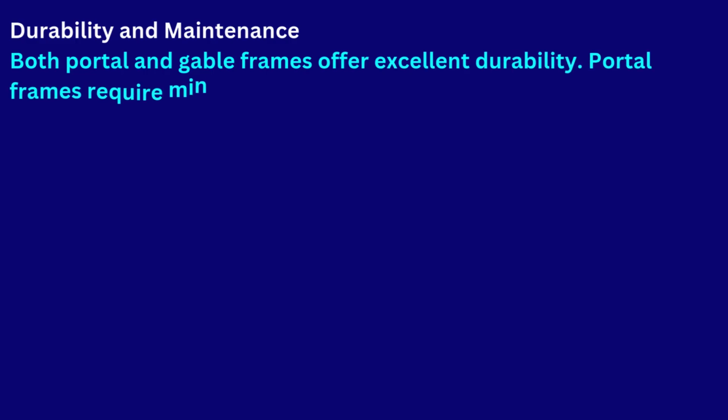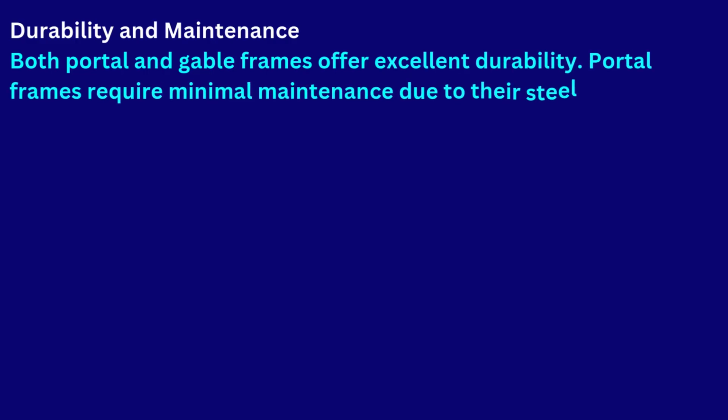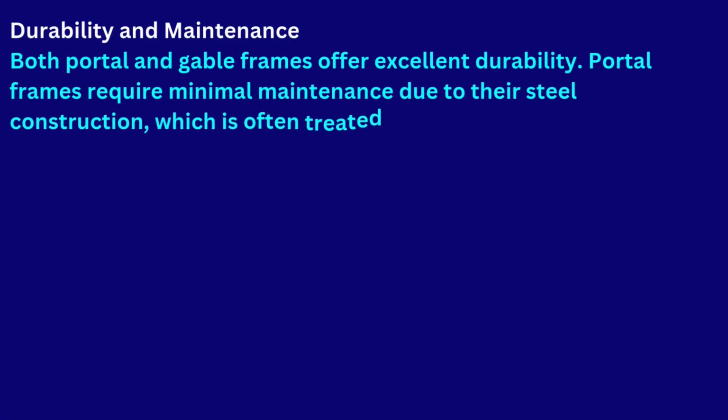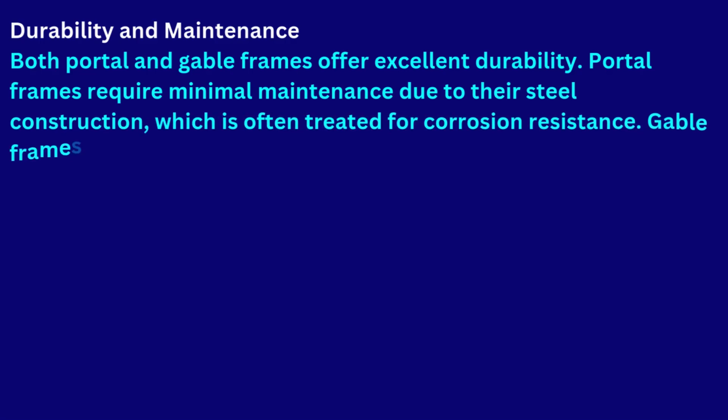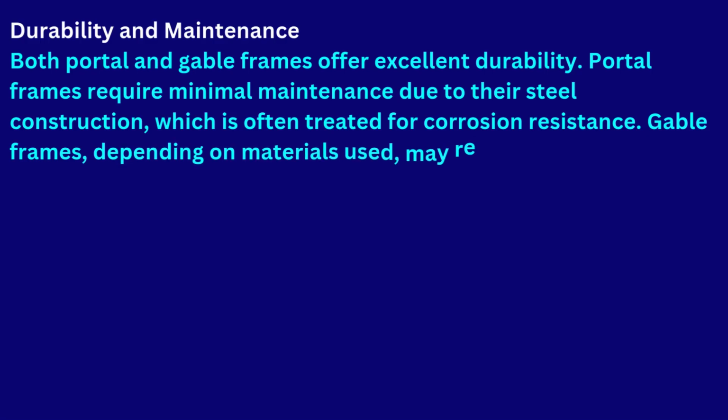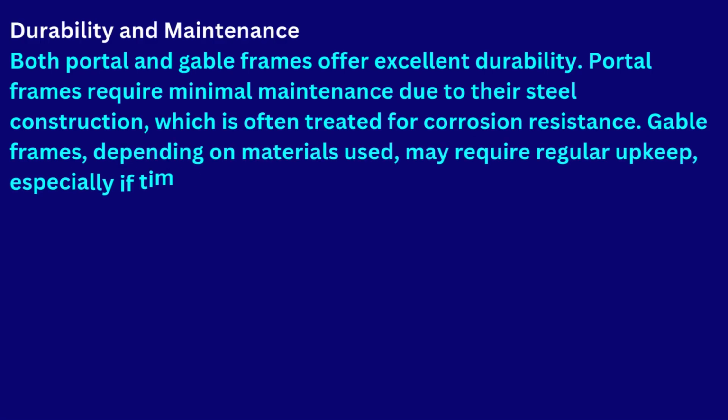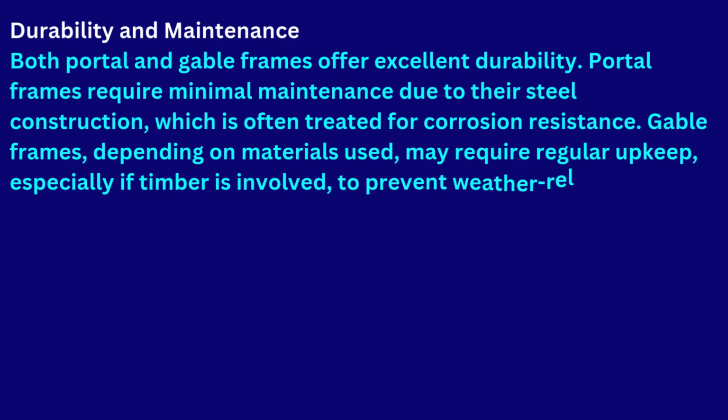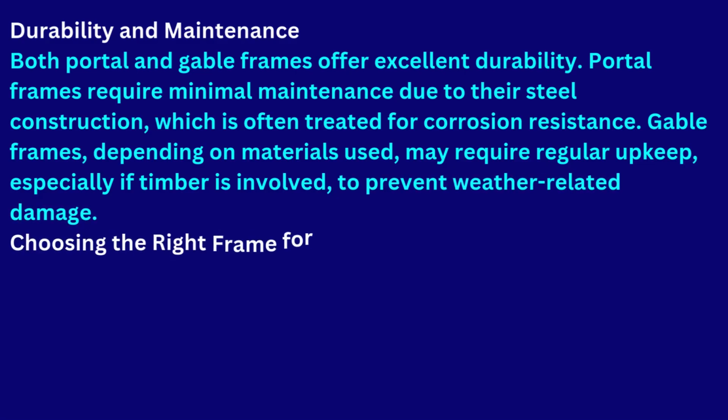Durability and maintenance. Both portal and gable frames offer excellent durability. Portal frames require minimal maintenance due to their steel construction, which is often treated for corrosion resistance. Gable frames, depending on materials used, may require regular upkeep, especially if timber is involved, to prevent weather-related damage.